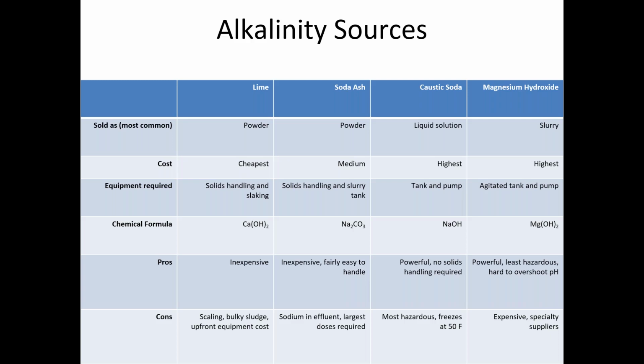Advantages to caustic soda here is it's very powerful. You get a lot of pH effect from it, and it's easy. There's no solids handling required. The drawbacks are it is more costly than the powdered versions, and it's very, very hazardous. This will do nasty things if it gets on you, so you need a lot of PPE to handle it